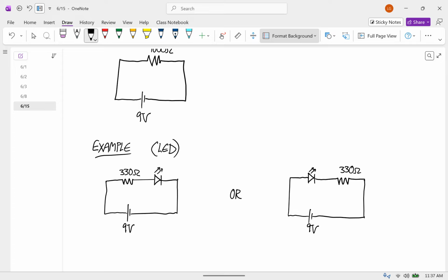Okay, why don't you try to put together a circuit using the breadboard and everything? And the resistor, oh, we're using the 330 ohm resistor, so that's the orange, brown. See if you can put together a circuit that lights up this LED. And I'll do it, and you can come up and look at mine if you have a question.